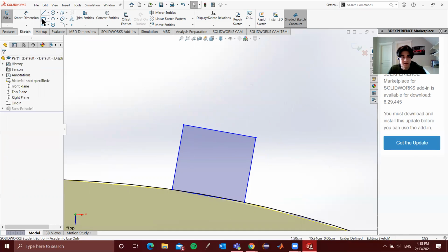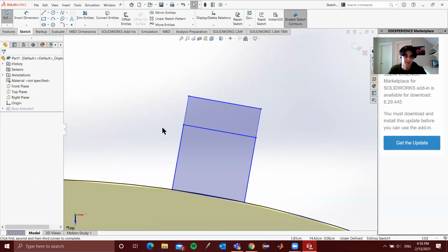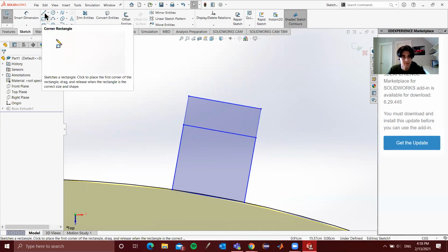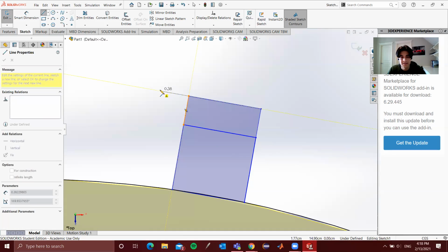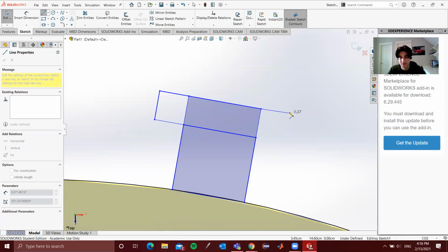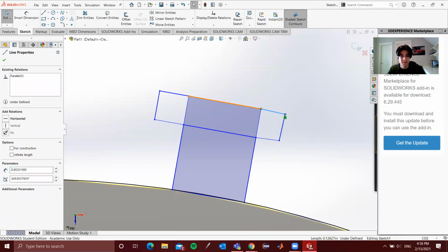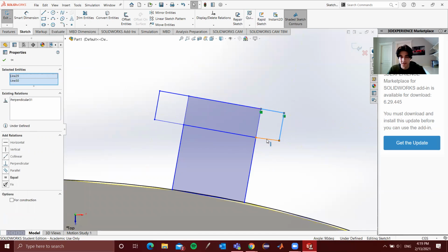So I'm just going to create a new square that extends like we did before. And then essentially extend this one outwards. So let's see. We'll create a couple of new lines and keep those dimensions that we had before in check. Working with circles can always be a little bit finicky, but hey, it is what it is sometimes. Okay, and we'll add our relations just to straighten everything up. So these two are collinear. This one's perpendicular. It's already perpendicular, perfect. And this one's perpendicular as well.